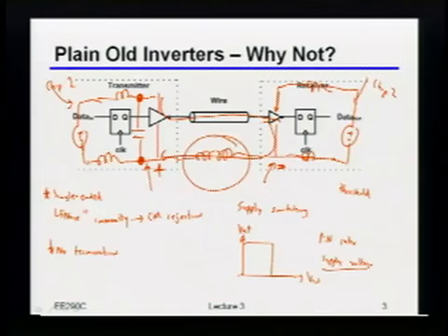So what I was getting at, and maybe those questions can be related to it, go ahead. Because when you say you have an inductance on the return path, you're assuming you have a single wire. But what about if you have a transmission line and the return path is part of the transmission line? Ah, but still basically there's an inductance associated with that, right? So even for you to have that transmission line, I had to have a ground plane and that wire, right? So if I think about the current that's flowing through that transmission line, it's always going to be flowing back through that ground plane. Yeah, right, but then it's more distributed, per se.